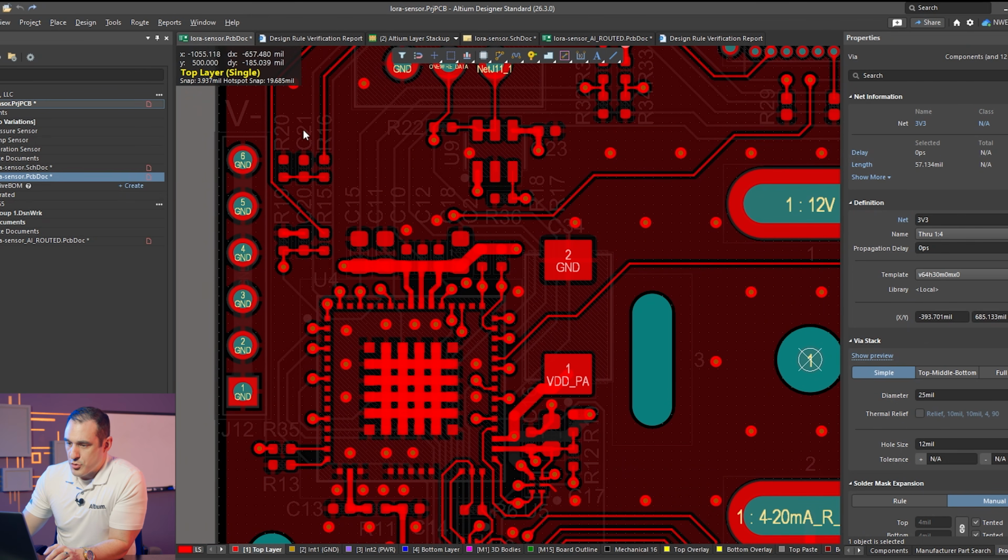Finally, a few things I would change. I would have considered just removing all of the thermal attachments. The reason is that I generally put things through reflow. I don't do hand soldering. But of course, if you are going to do hand soldering, having the thermal attach is helpful.